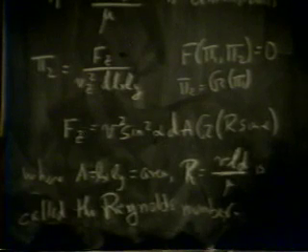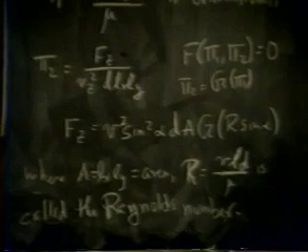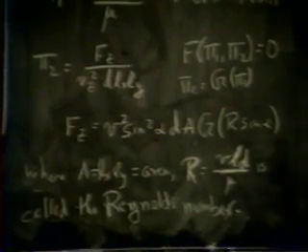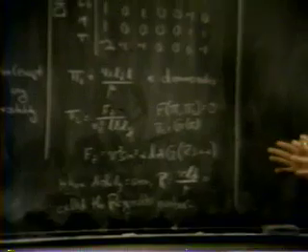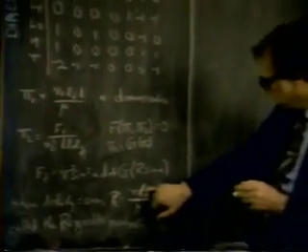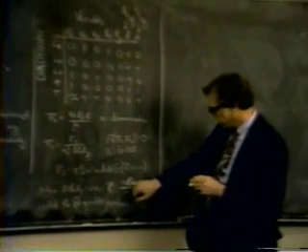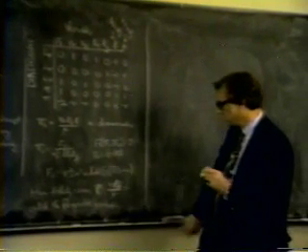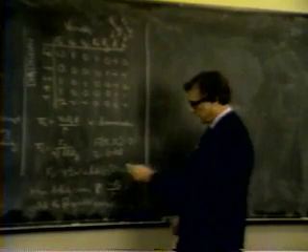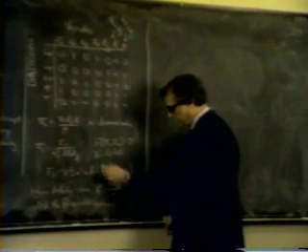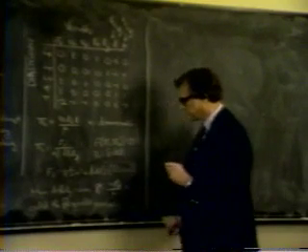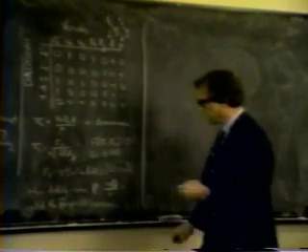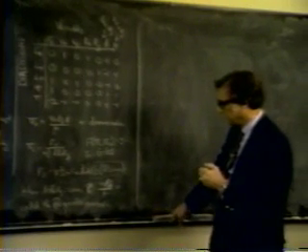Now, if we can find another fluid that we can use in a wind tunnel that has the same Reynolds number, that is, we'd like to make a small model of the aircraft we're dealing with, so we would reduce the L, and we have to compensate for that either by manipulating the density or the viscosity of the fluid we use or the velocity that's used in order to reproduce the same Reynolds number, then one can study the performance of the airfoil, because this quantity you can make equal to the value that you're going to deal with in the real world, and these dependencies, of course, are something that you have direct control over.